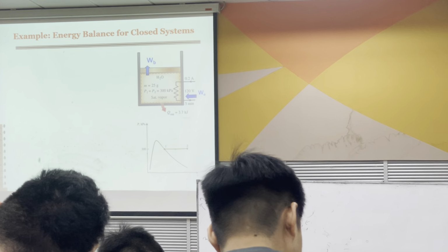So we sub in the equation here. From here, you move this entire thing to the right hand side. It becomes U2 plus P naught V2 minus U1 plus P naught V1. And when we group this together, from the pure substance chapter, we talked about this, whereby H equals U plus PV. So then we group this together, it becomes H2 and H1.